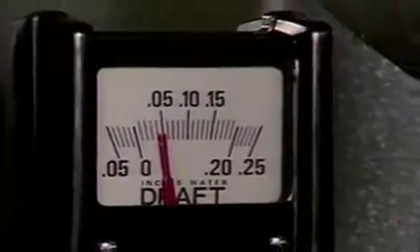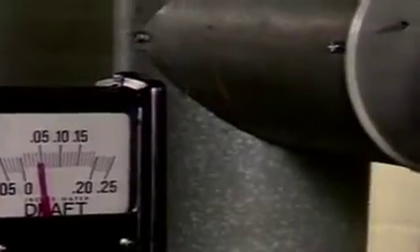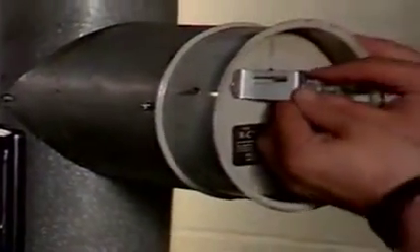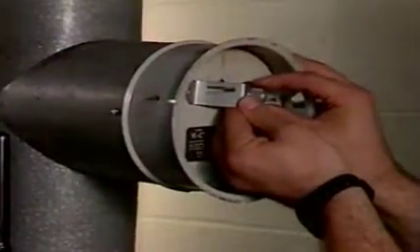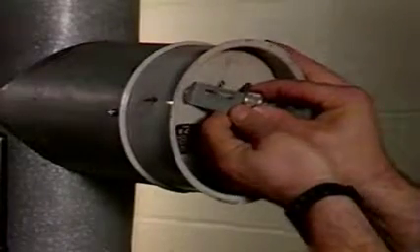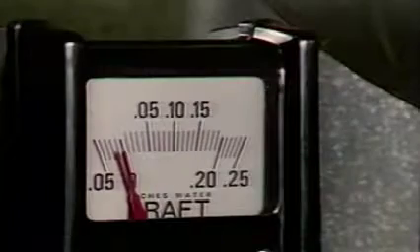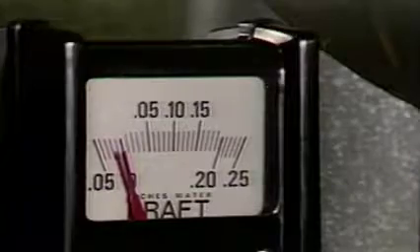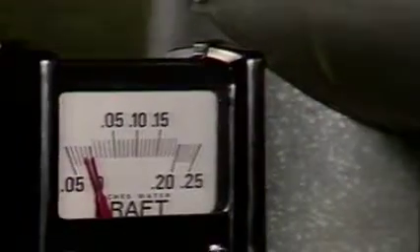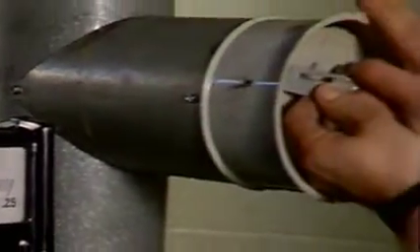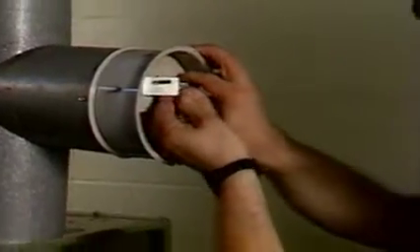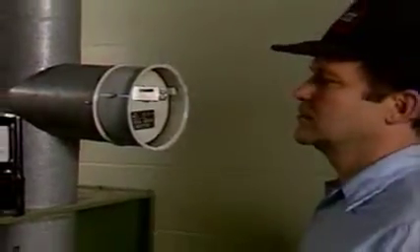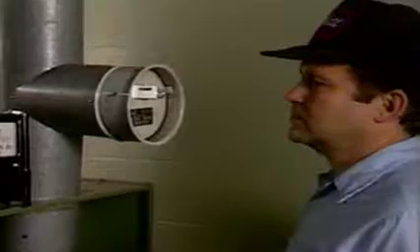Begin by taking an overfire draft reading. If the draft is higher than what you prefer, or that specified by the appliance manufacturer, adjust the regulator weight to allow the door to open more. If the draft is below -0.1 inch, adjust the regulator weight to just close the regulator door. If you cannot reach the -0.01 inch reading, a draft-inducing fan may be needed.